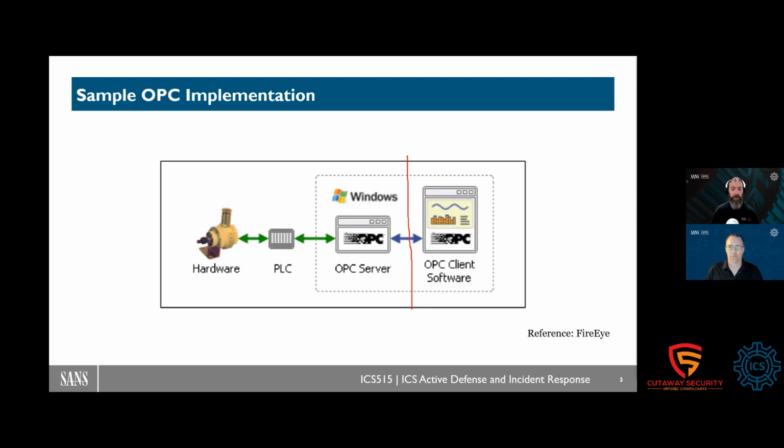And one of the OPC Foundation members is the OPC Training Institute. Not only have they got some OPC training, but they've actually got some tools like OPC Expert that you can use to understand OPC communications. Quite often it's used from an engineering perspective to establish OPC communications, like what around my COM or DCOM settings isn't set up correctly, what do I need to turn off from a security perspective to be able to establish communications.